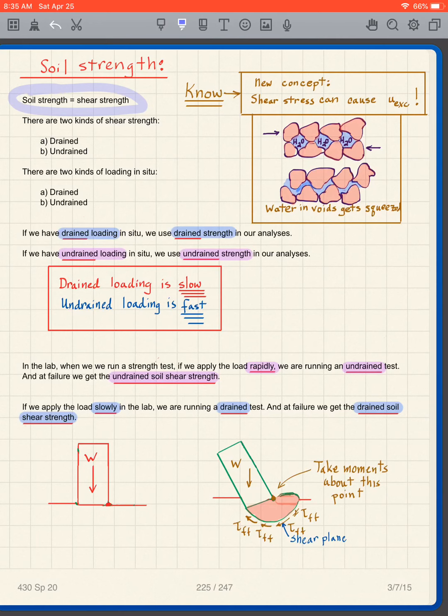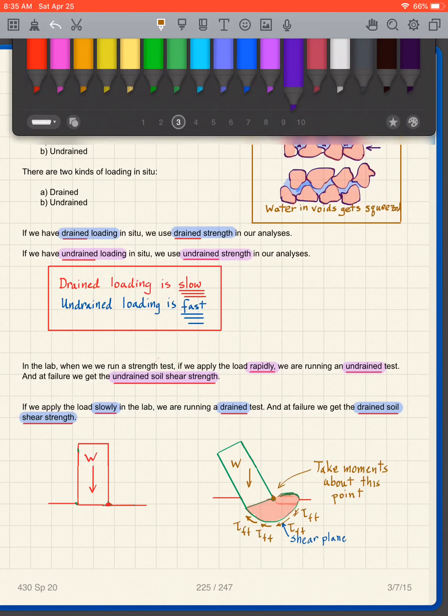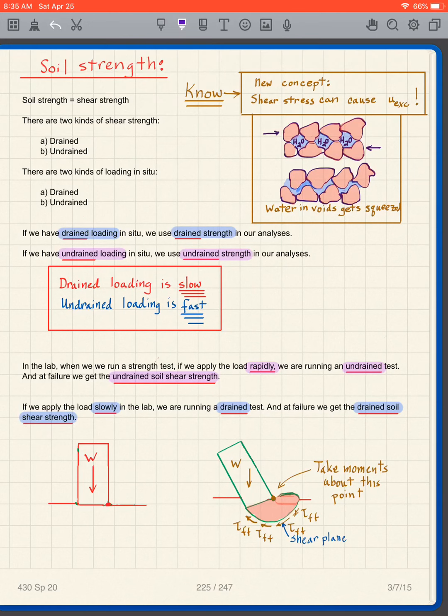So in other words, it contrasts with steel, for instance. If you talk about steel strength, you're talking about tensile strength. You don't mention it. You say, what's the strength of your steel? Well, automatically you know that when you talk about strength of steel, you're talking about the tensile strength of the steel. At the same time, when we talk about strength of the soil, without saying it, we are talking about the shear strength of the soil.